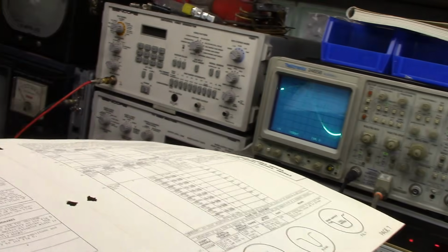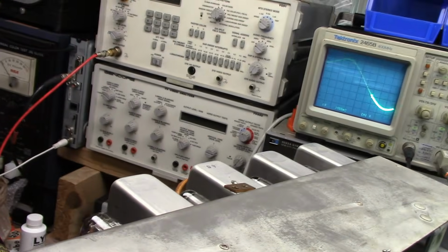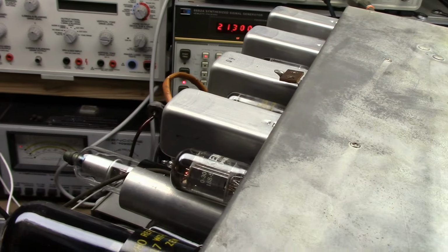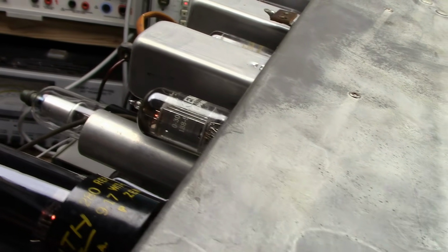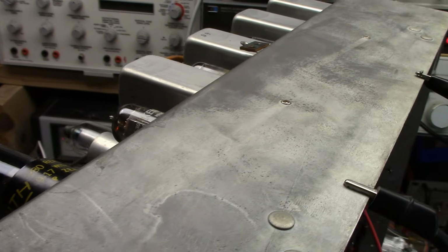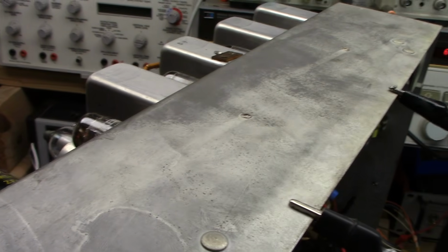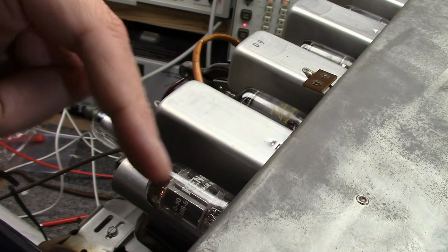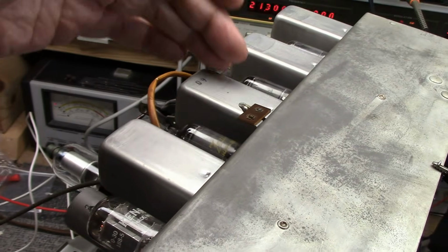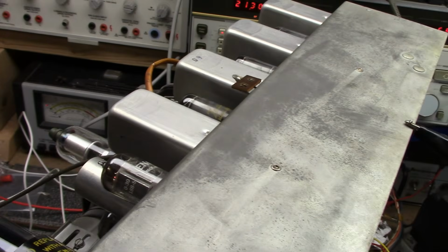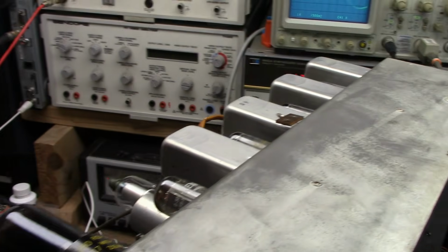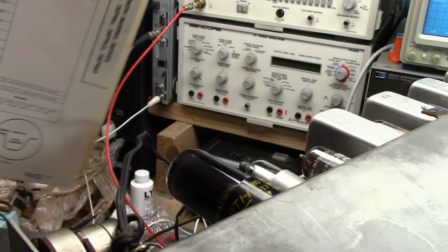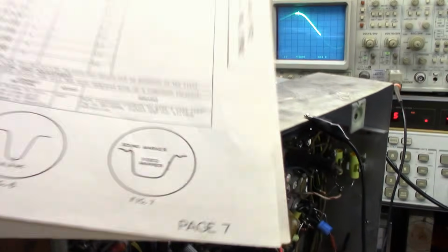These coils are a little bit tricky because there are 2 slugs, but you access both of them from the top using a hex plastic alignment tool. Let me grab one and see what we can do. So I'm injecting into this tube right here and sensing on the other side of it, and then we're going to work our way back. But right off the bat, we know we have some issues.